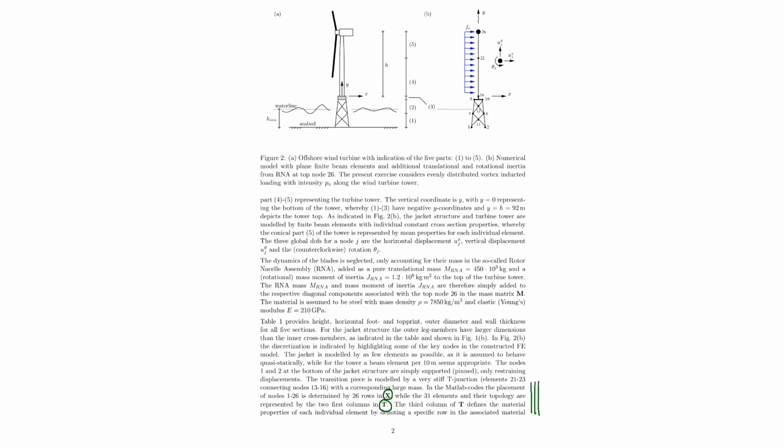As you can see on the top right figure, we only now consider a distributed loading, so no gust loading in this exercise. So it's only the vortex-induced loading that is considered. So we have a distribution of our load. It's evenly distributed, like we had in report number 1, and there's some kind of temporal intensity describing the harmonics of this loading.